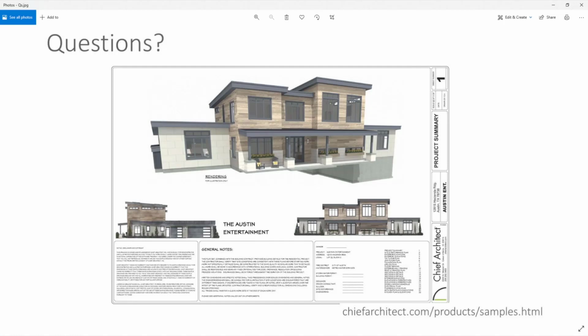And then I turn on the checkbox for lower wall if abutted by roof. And I'm doing it as an auto-built roof because it's going on the exterior of existing construction, and it's part of the house. So I have to make it look like an interior wall, correct?